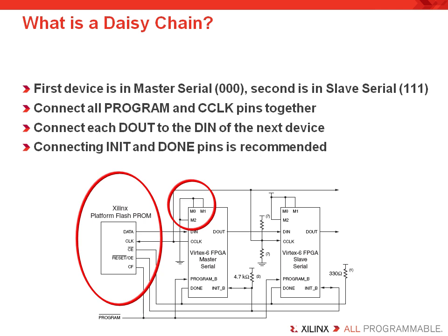We first have to connect the FPGA's clock and program pins to the corresponding pins on the other FPGA. The clock pins are tied so the configuration is synchronous to one clock. The program pins are all connected so that the entire system is reprogrammed on command by the user. There's no point in reconfiguring one device. You've got to reconfigure the whole system.